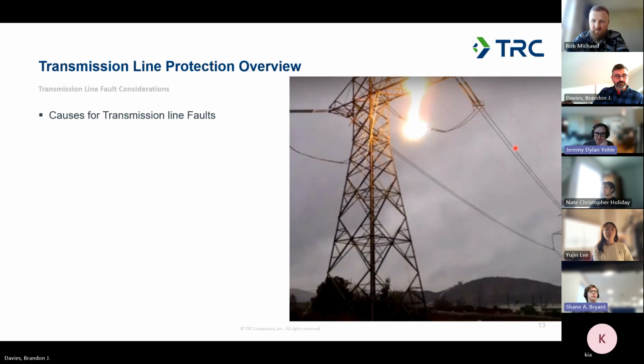Like extreme weather. Definitely. Yeah, extreme weather is a big one. If you have wind and ice, if you have a wind blowing intermittently, you can have these conductors actually swing. I mean, they're not static, stretched so tight they don't move. They can actually move, and you could have them move and connect to each other, and that would cause a fault. Any other thoughts?